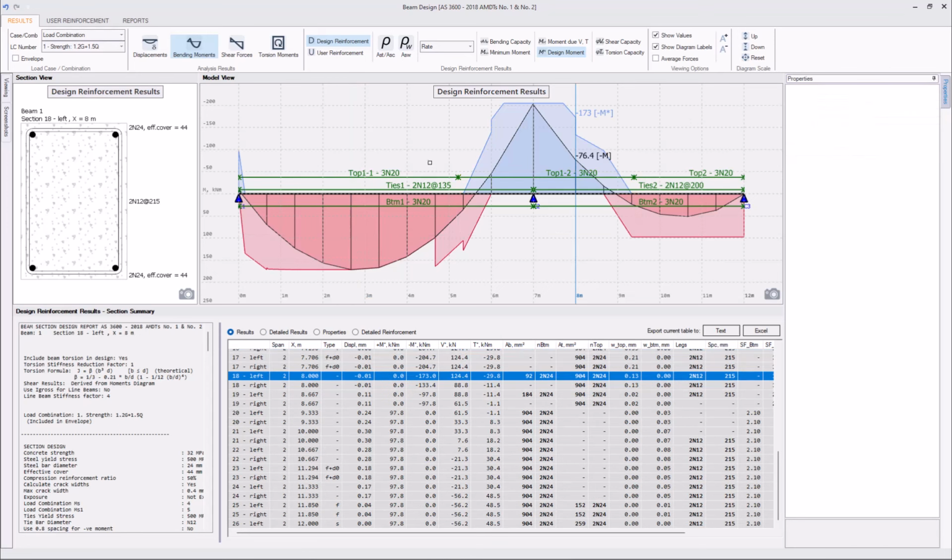And we can have less reinforcement along the mid spans. So for example, let's change the label as well. T1 will have 2 N12s for the first span, and also that'll be T3, 2 N12s for the right span, and I'll leave 3 N20s above the support.